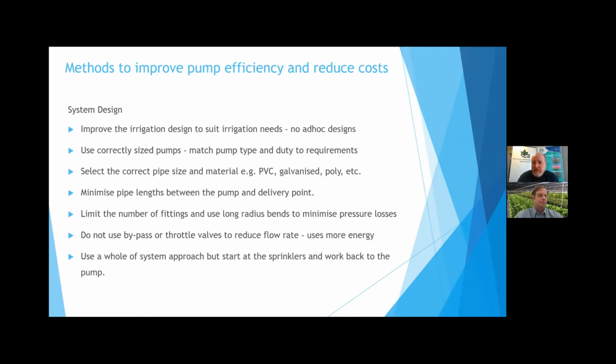Make sure that you've got nice straight runs, fluent bends, no major crazy pipe work. The more bends you put in there, the more elevation there is, the more friction there is, the more energy is going to be needed, the higher the cost of pumping will be. Also, if you're using lay flat hoses, although they can be useful at times, they have a very high friction coefficient, and they will cause your pump to use more energy. So if you are permanently using a lay flat hose and you can replace it with a solid pipe, then do so.